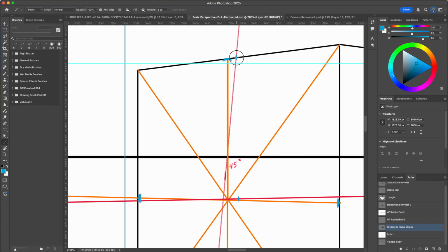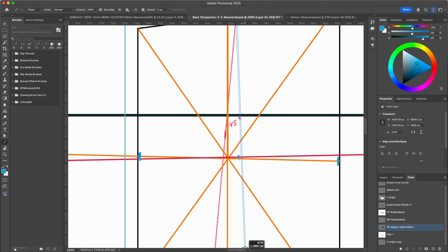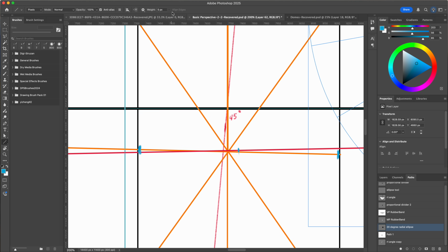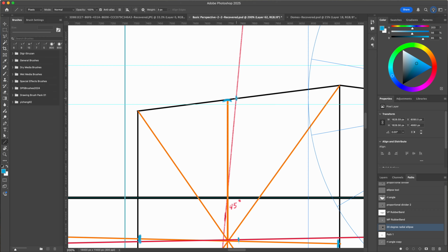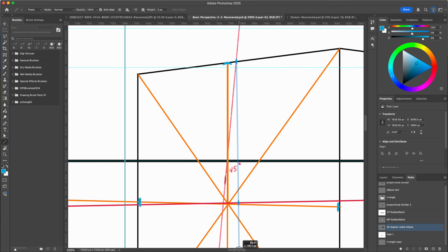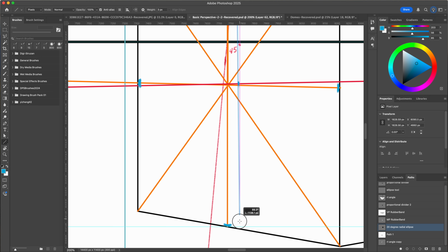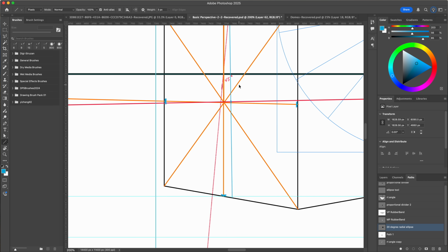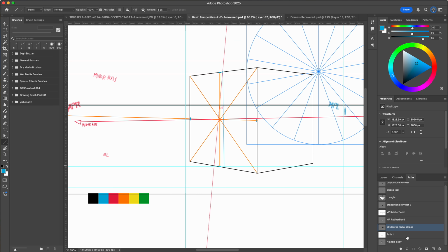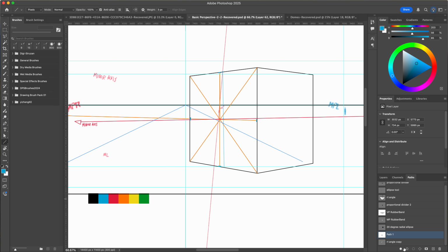So I can just go from this point with this straight line. You know what? Let's make that smaller. We'll make this a 3-point width on this. Okay. So if I come right through this here, all right. So we're originating up there, and we're going right through that minor axis at the measured center, 90 degrees relative to the minor axis degree, right there. Okay. So that is going to be the major axis of our ellipse. That's the major axis of our ellipse right there.